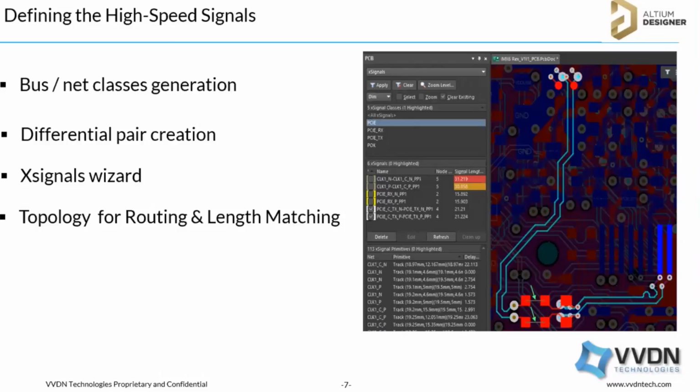If it is high speed, how am I going to route my signals, right? For example, it can be a daisy chain topology or a T topology. Consider you have one processor and two DDRs. Now I'm going to route the signal and match the signal from source to one DDR and then the next DDR. That is daisy chain topology. I thought of adding those images, but I forgot. But you can make a note and Google it. You will get a lot of images or references for the topologies. Okay, T topology and daisy chain topology.